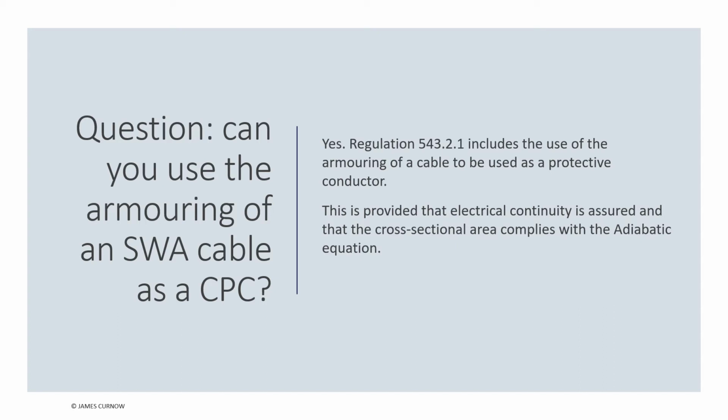There are some sizes of SWA cable that would not comply with the adiabatic equation and would not be possible to use as a CPC. So we first need to carry out the equation in table 54.7 of BS 7671 to ensure compliance.